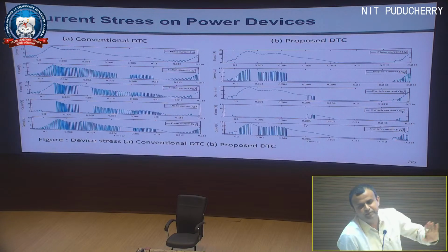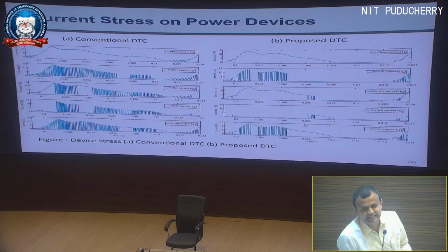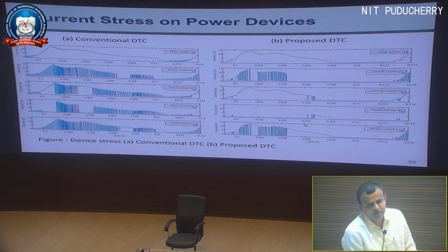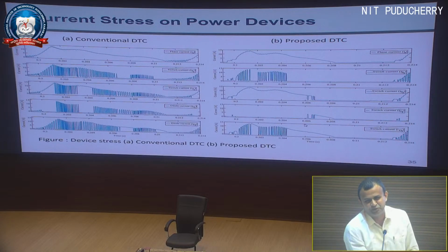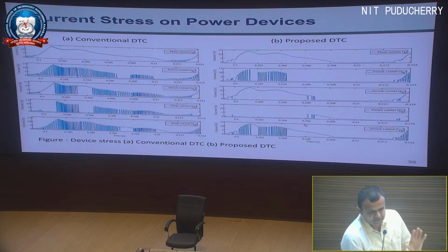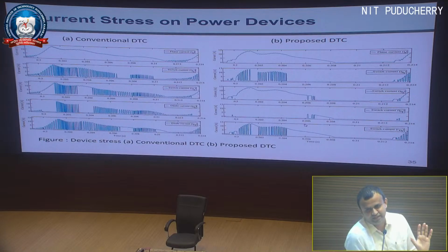Not many people concentrate on these things, the stress and the thermal management, the heat sink. Even my students usually just look to see where a heat sink is available. They will not worry about the size or the thickness. They immediately apply some thermal paste, put the device, screw it, and put it on the board. That's all they do. But actually we have to properly work out how much heat it will dissipate, otherwise you may end up losing that device.